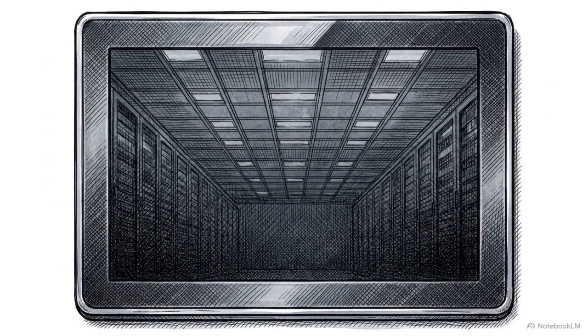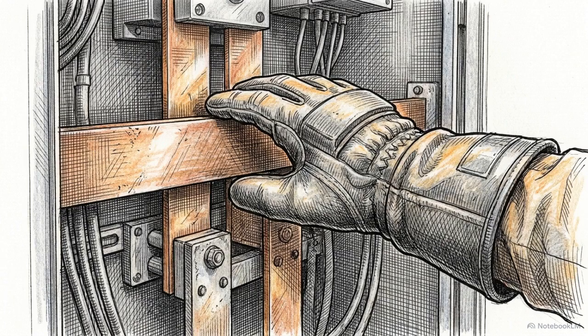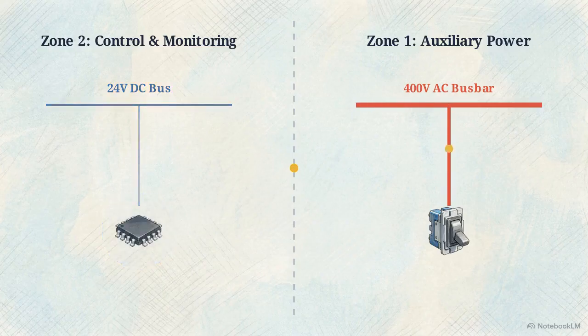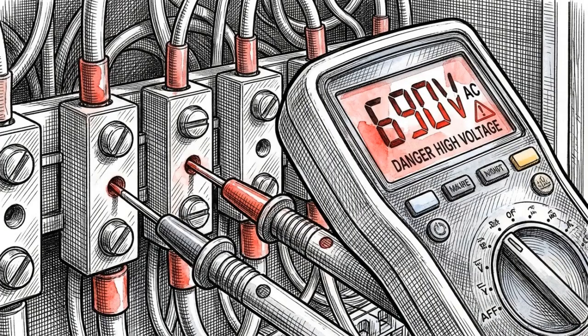This procedure highlights the boundary of the digital interface. The touchscreen is highly accurate, but remains a monitoring aid, not a guarantee of physical safety. An on-screen reading of de-energized cannot be used to authorize physical contact with electrical components. While a dark screen proves the internal low-voltage DC bus is dead, it proves nothing about the state of the heavy AC terminals or the upstream feed.